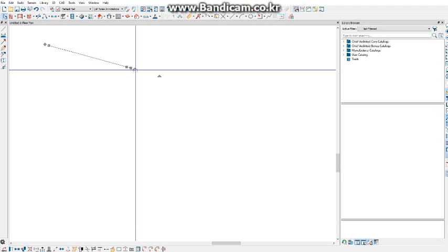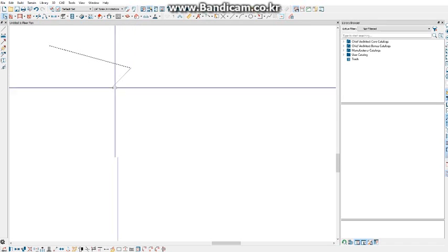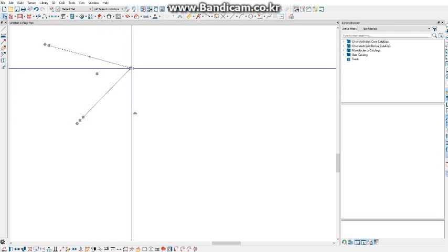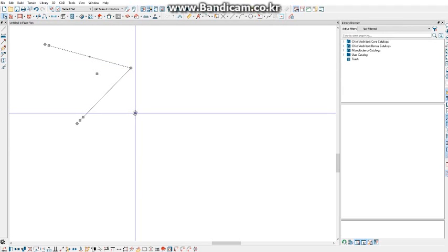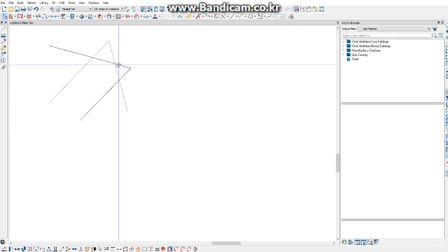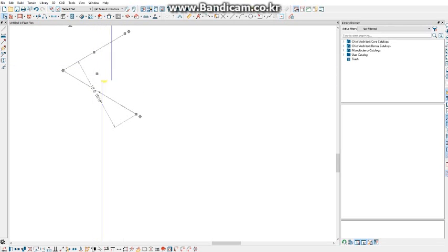The Diamond edit handle is the Draw the Same Line type edit handle. If I click and drag this edit handle in a different direction, it'll draw another line connected to the endpoint of the first line. You also have your Rotate edit handle, the triangle beyond the object. If you click and drag this in a clockwise or counterclockwise direction, you can rotate this object.